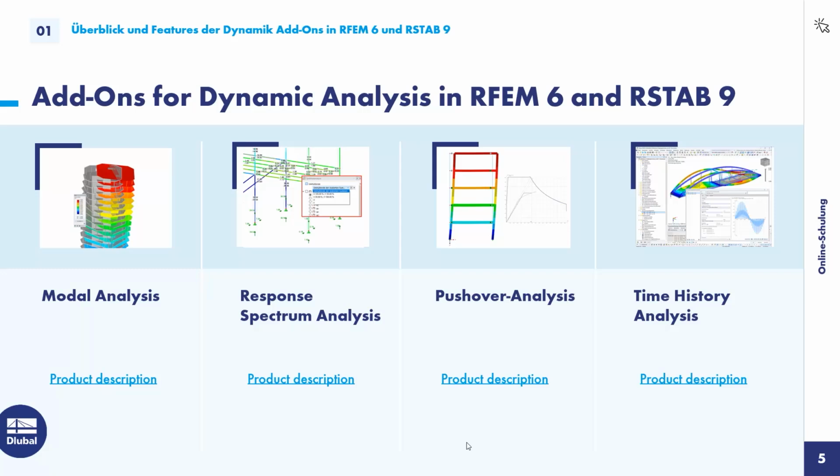Currently, we have implemented the N2 method for the calculation of the performance point. That means the performance point is the point of maximum deformation the structure is estimated to have under the defined response spectrum, so under the defined seismic loading.